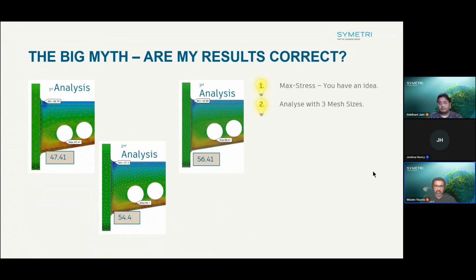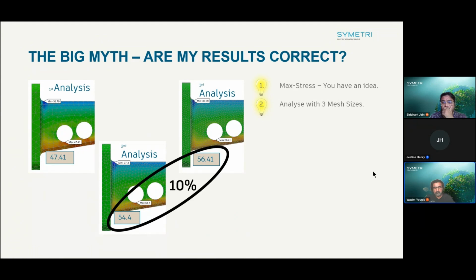And the idea is what you're looking for is the stress results difference. Now, for your own benefit, there is no difference in displacement results. So if you're interested in looking at the displacement results, then one analysis is more than sufficient because displacement results do not tend to change as you change the mesh. It's primarily the stress.